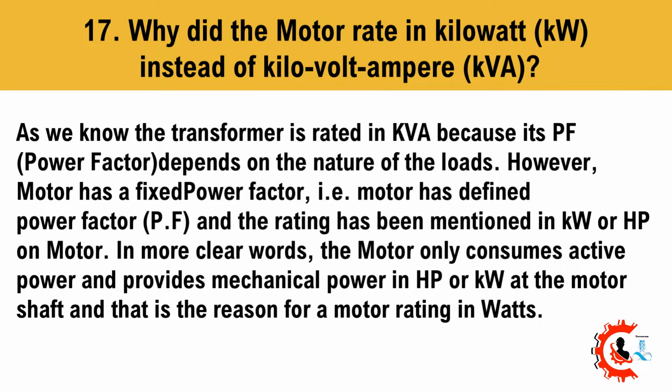17. Why is the motor rated in kilowatt instead of kilovolt-ampere? As we know, the transformer is rated in kilovolt-ampere because its power factor depends on the nature of the loads. However, the motor has a defined power factor, and the rating is mentioned in kilowatt or horsepower on the motor. In clearer words, the motor only consumes active power and provides mechanical power in horsepower or kilowatt at the motor shaft, and that is the reason for a motor rating in watts.